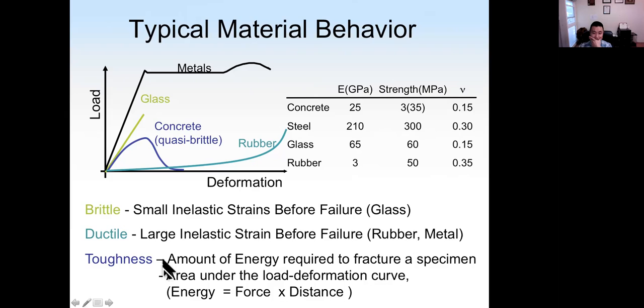For concrete, we also have an elastic region, but after around 30% of f'c, the slope will become smaller. And after the peak load, the concrete will fail, but not fail suddenly like the glass. It will have some resistance to deformation until the final failure.